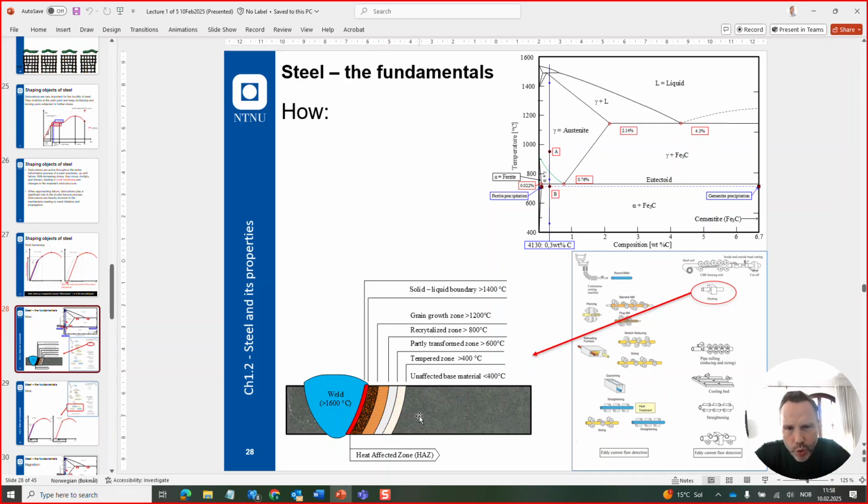So line pipe or what we call conductor would typically be welded, and then again the medicine and the mitigation to avoid the problems of having grain growth would be recrystallization. We have to do heat treatment.